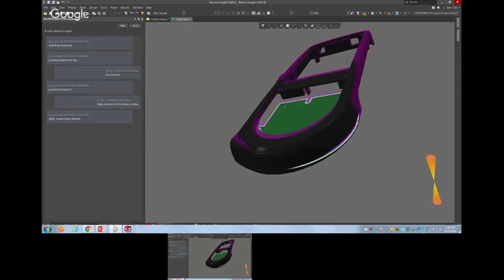Got a question on holes. Plated through and non-plated through. Yes. They actually have standardized holes, M3 clearance holes that actually have keep outs. Will you be able to see the keep out on the SolidWorks side? Okay, the question was with holes. There are M3s and holes with keep out, and would we be able to see that on the SolidWorks side? On the SolidWorks side, yes, you'll be able to see it. The problem is that when you push this information over to the electrical, will they see those keep outs? Today, no. Considering it in the future, yes. So this is coming in as a whole.